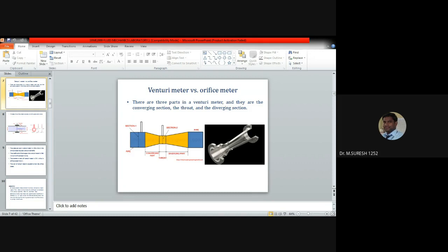But the readings and calculations are similar. You should also know how to find the calculations and the unknown values, and that calibration of the orifice meter means determination of the coefficient of discharge, the CD value. You should also know the difference between actual and theoretical discharge.